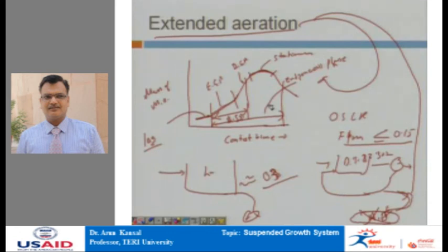Therefore, the biomass synthesized at the declining growth phase contains a small fraction which is not biodegradable and accumulates as sludge in the system. The excess sludge thus produced is highly stable and can be directly dried over a sludge drying bed. So, here we can supply it directly to the sludge drying bed.